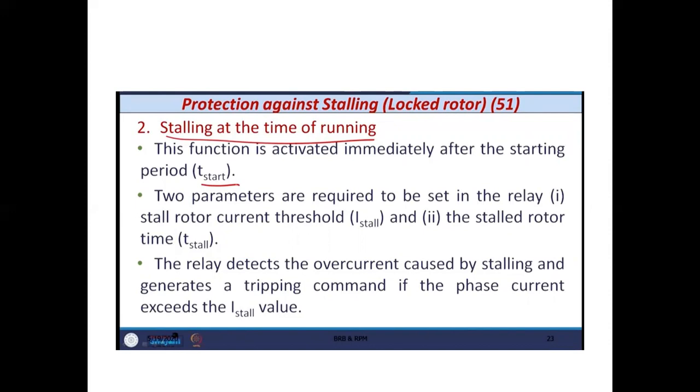And the second is the stalling rotor time, that is T stall. The relay detects the overcurrent caused by the stalling and generates a tripping command if the phase current exceeds the I stall value.